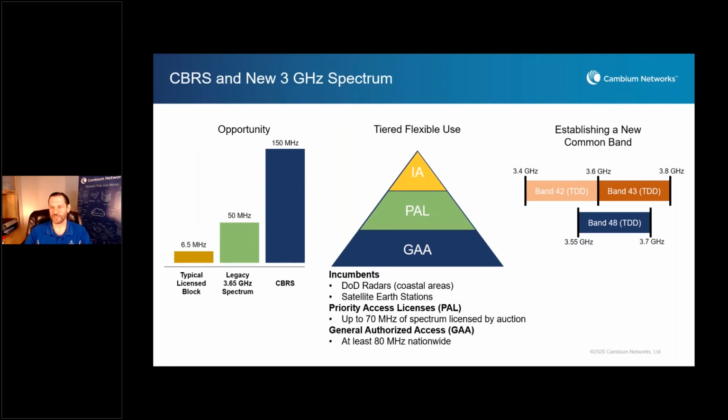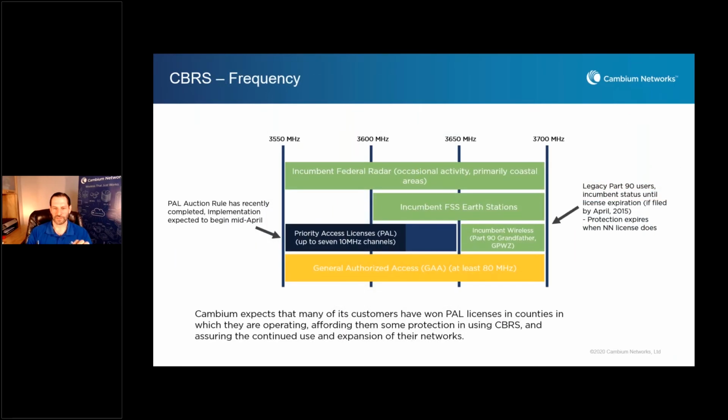They established a new TDD LTE band called band 48 to accommodate this. In most of the world, band 42 and 43 are still going to be used for the 3 gigahertz spectrum. So in most of the world, there's 400 megahertz of spectrum to use, which can be used in this sharing model. I will say that in a lot of countries, those two bands, 42 and 43, are already allocated to either mobile users or are strictly licensed, and may never see this sharing model adopted. But there are countries that are exploring that now.